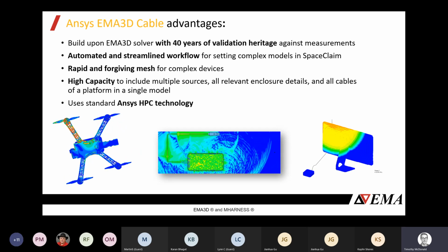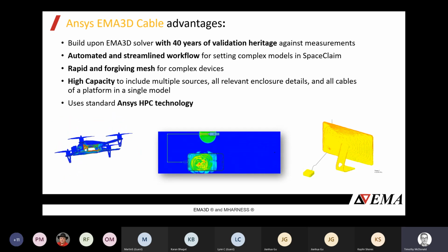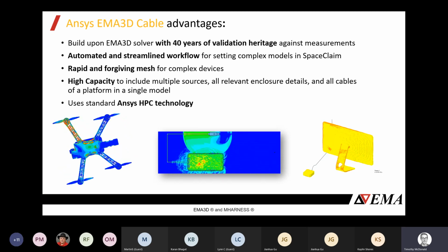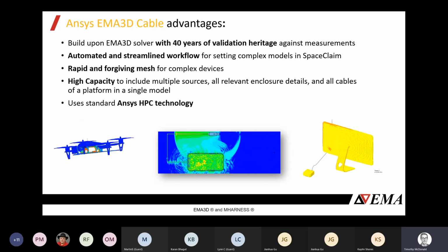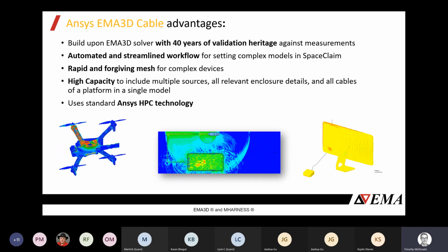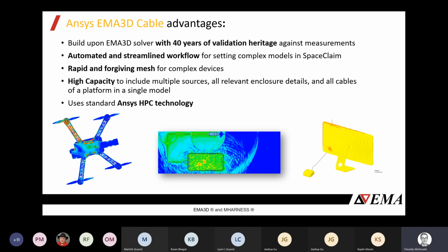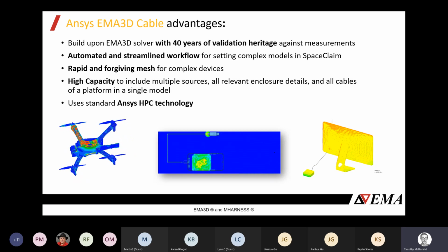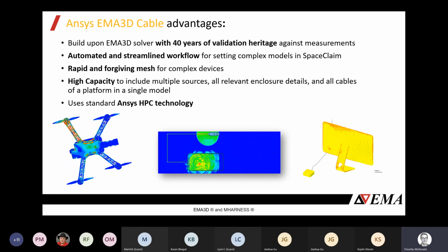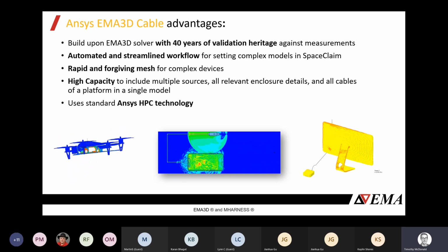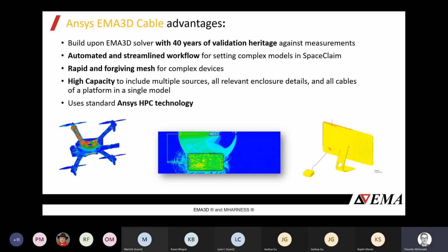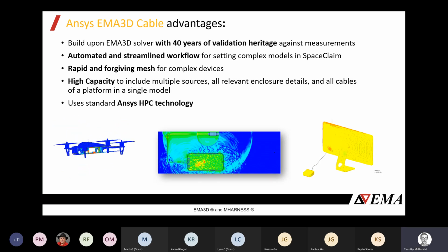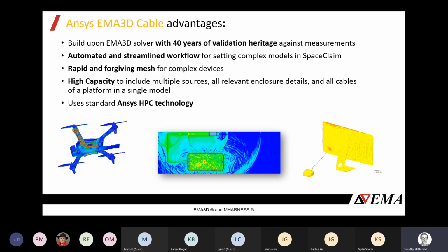And by adding 3 new features, the Nexxim Transient Circuit Co-Simulation, the ability to export libraries of material properties and cable cross-section definitions, and finally to control custom terminations of cables and allow conductors to break out of shields, we've added to the features to expand what is possible and what can be modeled as we move toward the goal of doing all EMC testing via simulation to reduce risk and cost for EMC testing.